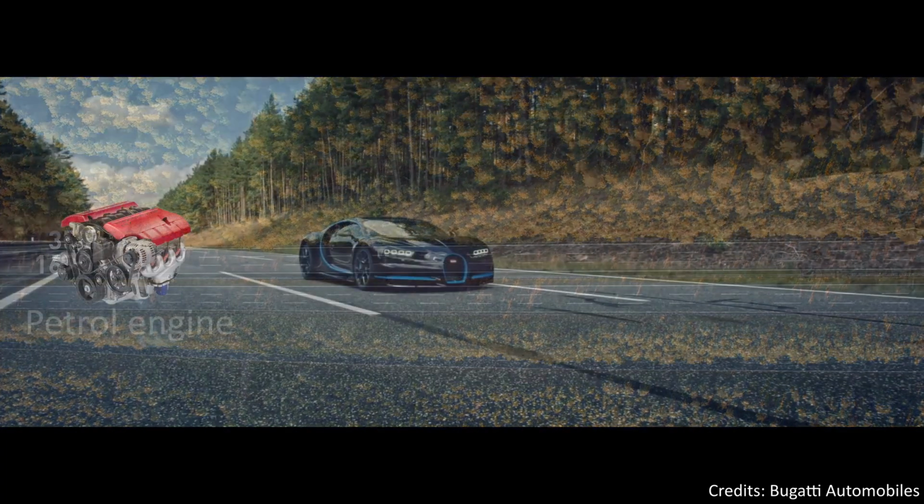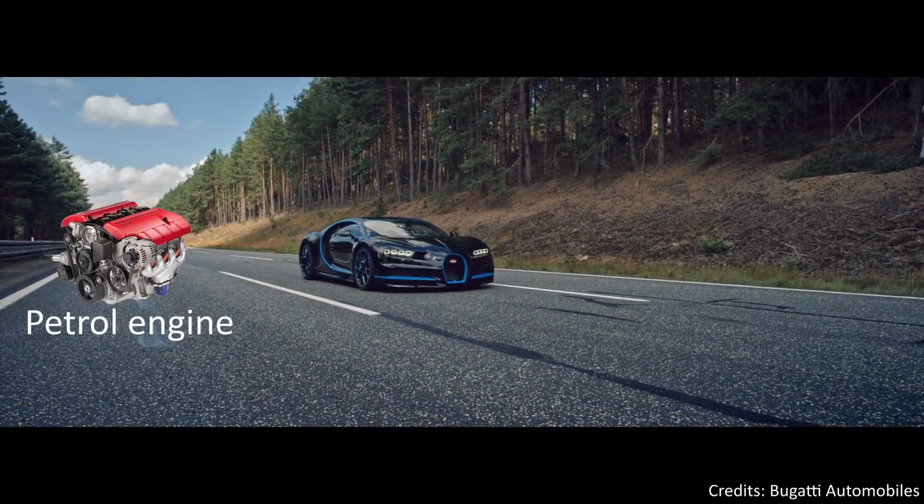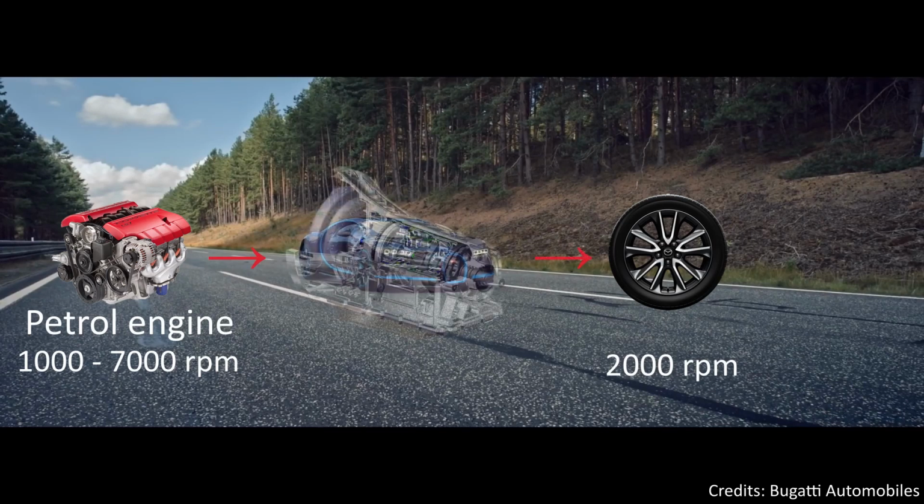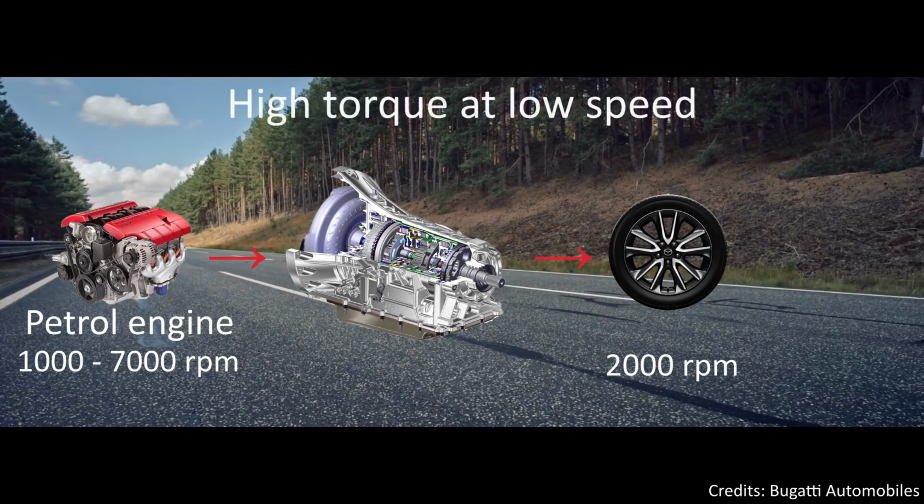For example, a petrol engine operates at very high rotational speed, usually over a range of 1000 to 7000 rpm, while the wheels rotate usually at a maximum of 2000 rpm. So the job of the transmission system is to reduce the higher engine speed to this lower wheel speed. This process is useful in order to increase the torque, so that the system can supply high torque at low speeds, but also stay within the engine RPM limit at high speeds.